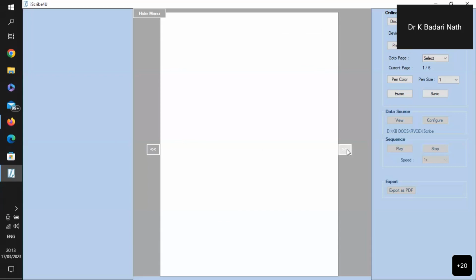Why do we have to understand the instruction? Once you understand it, you can get an idea whether any memory operand has to be fetched as part of the instruction. Any instruction execution always requires first fetching the instruction into the processor, and then, if required, the operands have to be fetched, and then you perform the operation. The sequence will be similar. So now we have completely understood how to write the control sequences for execution of different instructions.